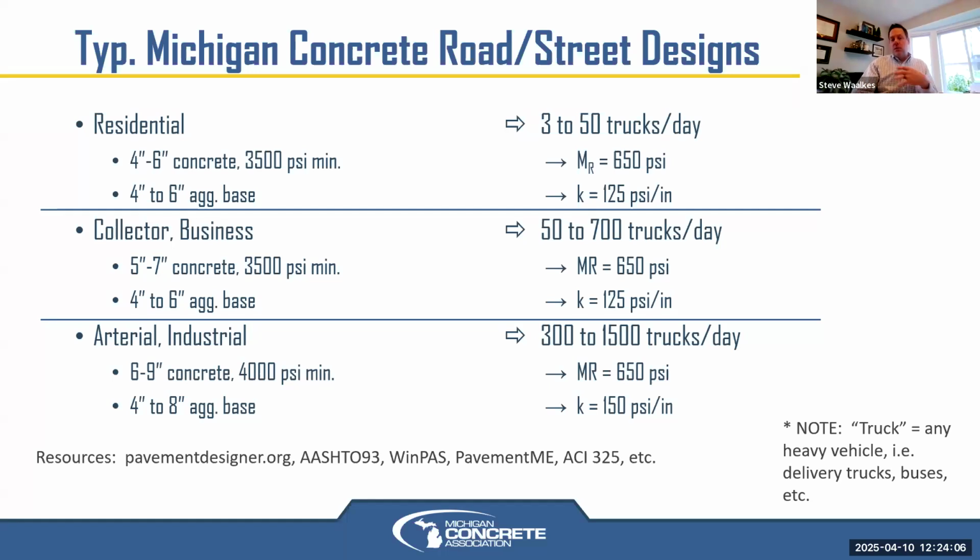So in general, the rule of thumb that we tell folks is if you have a concrete slab and you add an inch, you can almost double the traffic load carrying capacity of it, whether it's the weight of the vehicles or the number of axles driving over 20 years, however you want to characterize it. It's a good rule of thumb.